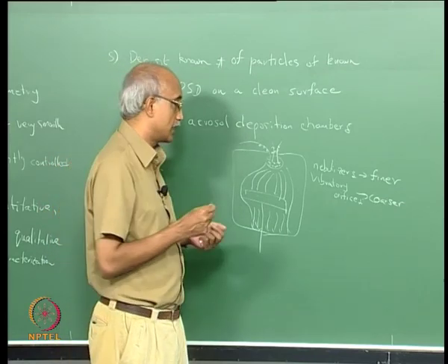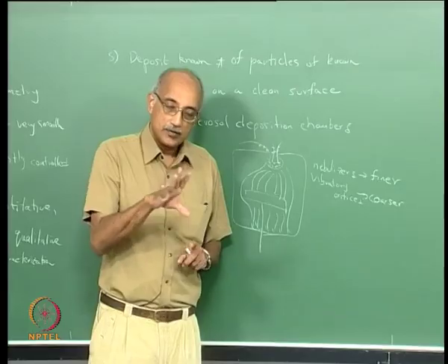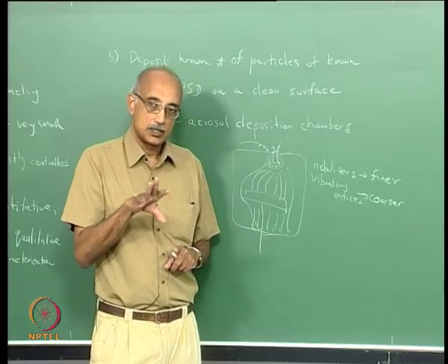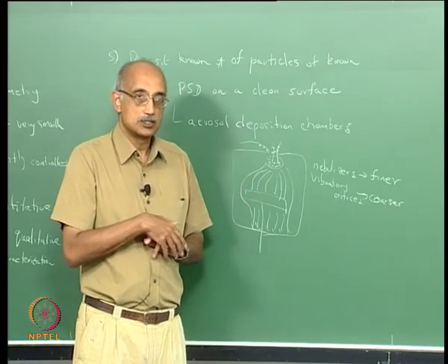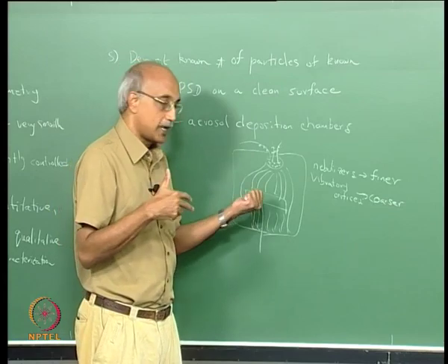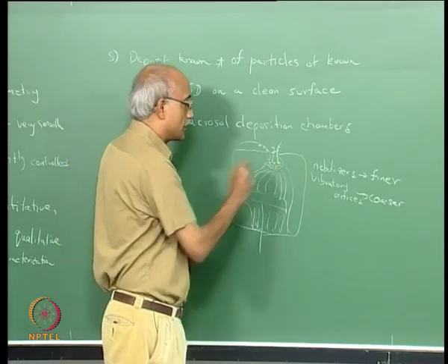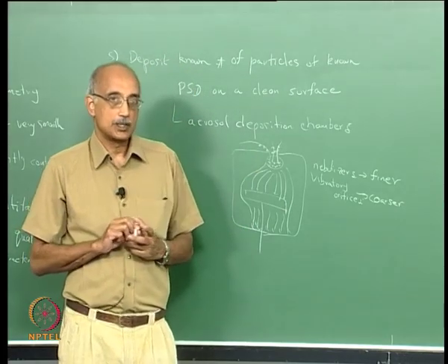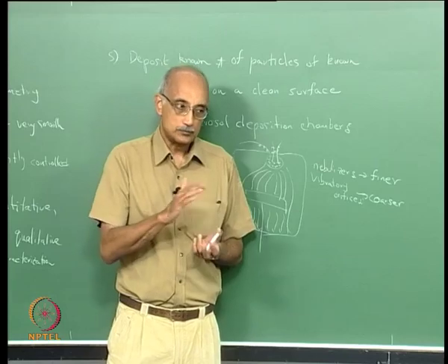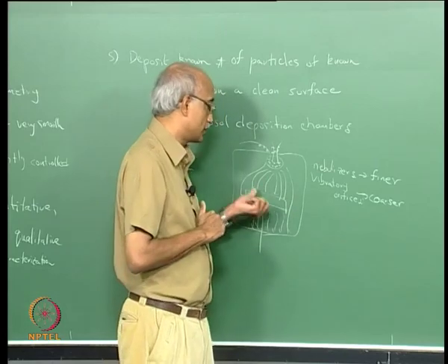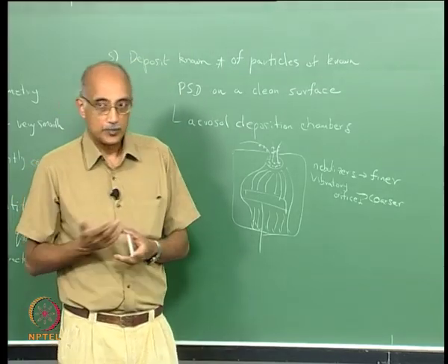You have to ensure that particles, when they leave the orifice, are being delivered at a constant velocity, because especially in the case of larger particles, the velocity determines the impact potential to the surface. So, the output from the nozzles should be tightly controlled in such systems in order to ensure that the particles are delivered to the deposition surface in a repeatable and reproducible way.